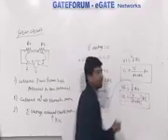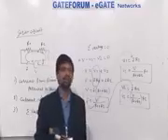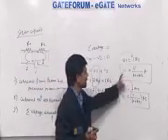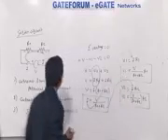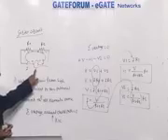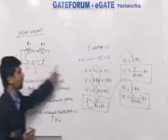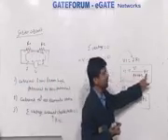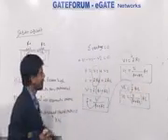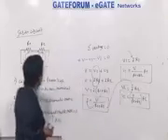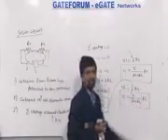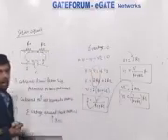So what is the very important property of a series circuit? If you observe these two expressions properly, then one can say that V1, the voltage drop across R1, is the total applied voltage V into the same resistor value R1, divided by R1 plus R2, the summation of the two resistors. Similarly, V2, the voltage developed across R2, is V into R2 divided by R1 plus R2.